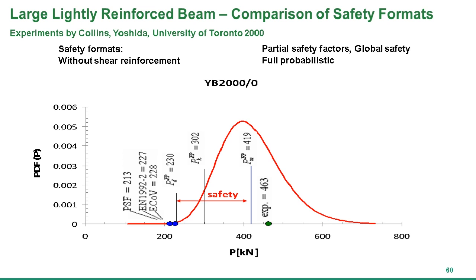Of course, there are some situations which have been reported where these methods don't behave that nicely, and this is still under discussion. Just for your interest, here you, for instance, see the formulas for this beam from the current Eurocode and, for instance, from the ACI code. So we can also see that even in the current formulas, we have, let's say, problems in some particular situations of very deep and lightly reinforced beams failing in shear.